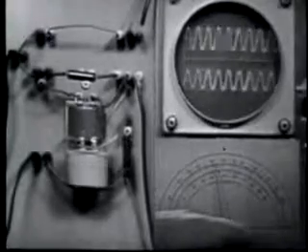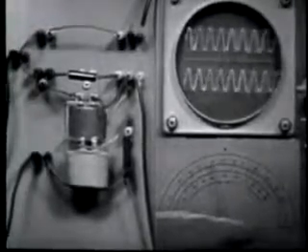At frequencies off resonance, the parallel tank impedance is minimum and passes these frequencies through. The series tank impedance is maximum and develops the output voltage. The circuit is passing frequencies off resonance. And note the extremely sharp response, since we're now using two tank circuits.